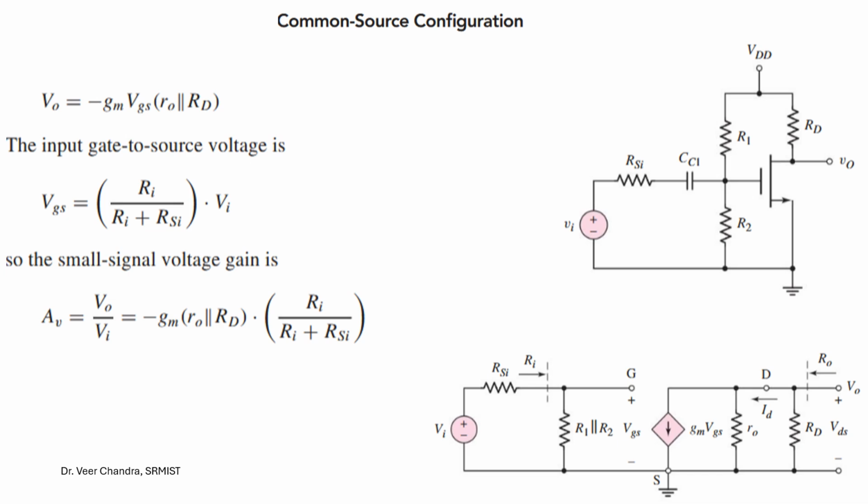Again our objective is to find the gain, that is V out by V in, also called the amplification gain. With the help of the equivalent circuit, we first replace this configuration with the AC equivalent circuit. It is very easy to draw: first replace this MOSFET with VGS open circuited, then the current source of gm into VGS and r0 in parallel with it.